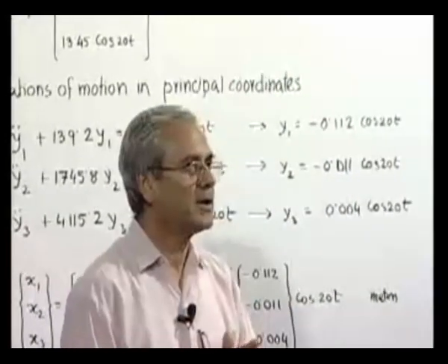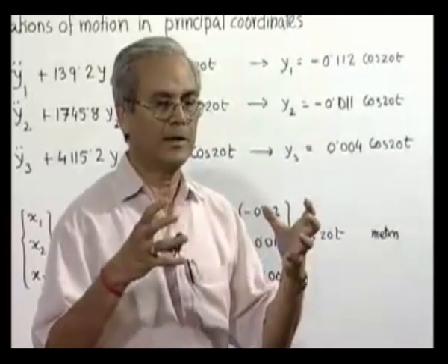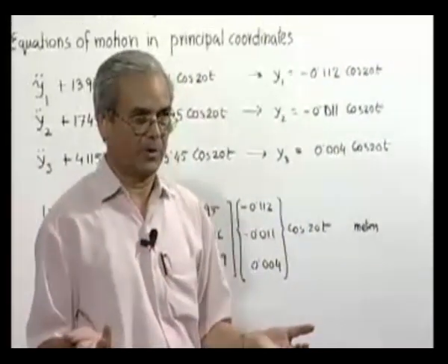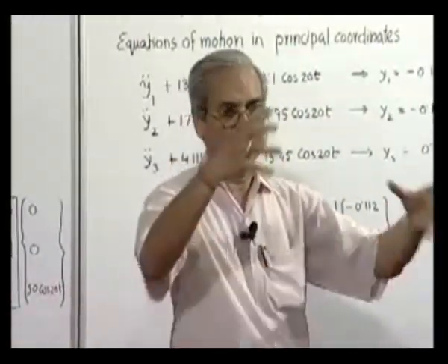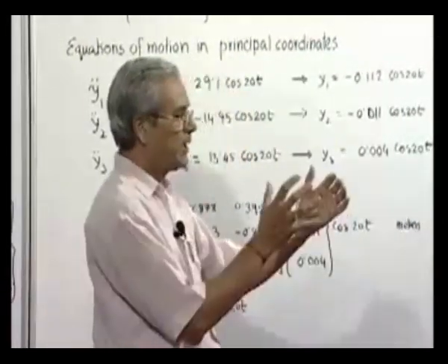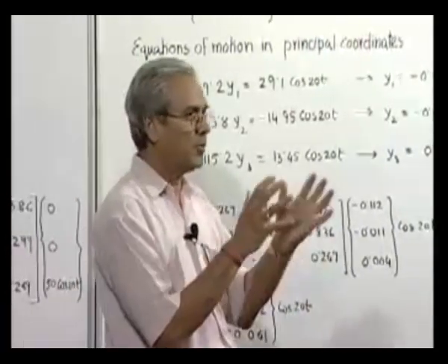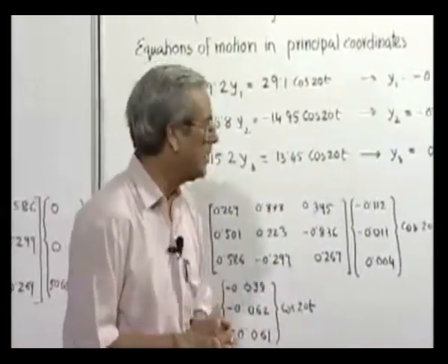Now, multi-degree freedom systems are obviously, as we have been mentioning, an idealization or modeling of the real system. That means a beam with various cross sections, or a machine, or a structure. We can model it in the form of a lumped parameter system, which will be approximately representing the system.